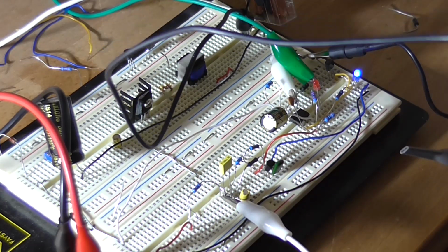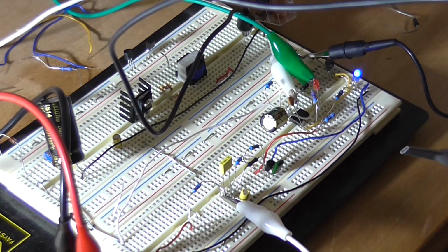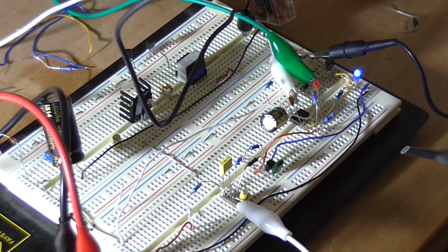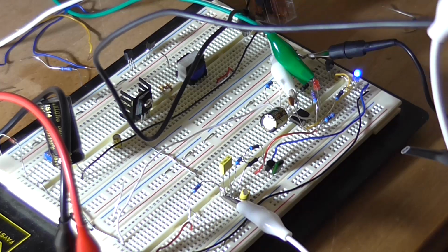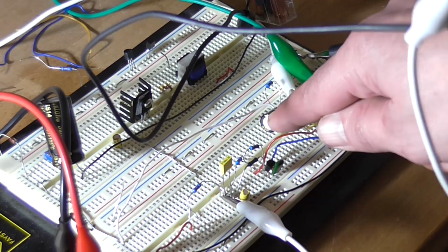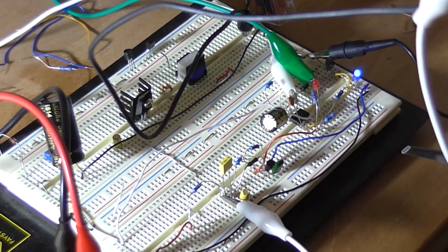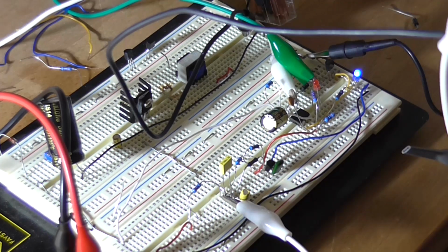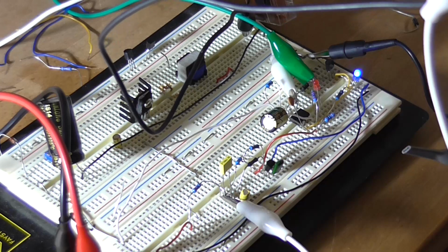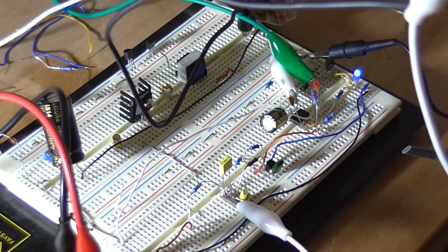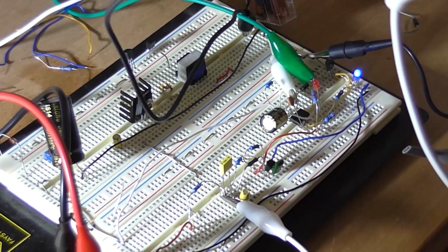So if I was just to talk normally into the microphone, which I'm doing, and I'm about 5 centimeters away from my mouth, and I'm talking at a reasonably normal level, it's still sensitive enough for the circuit to pick up, although if I pause too long, this capacitor charges quick enough for it to reset the circuit. So yeah, see what I mean? So there's no real way to overcome that issue unless you add an extra transistor to keep this capacitor discharged whilst it's receiving a signal.